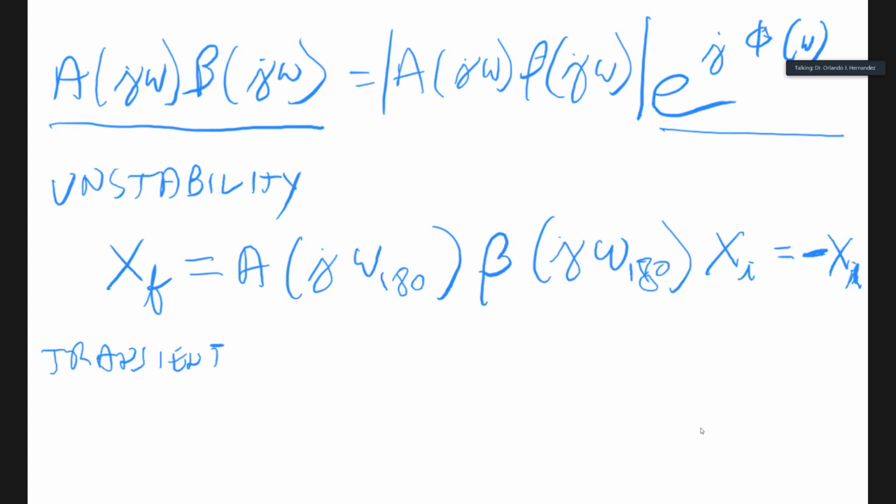Exactly. Those nodes are standardized with those labels. That's just saying that now the error reverses polarity, and now it is feeding with the wrong sign into your basic amplifier, therefore producing a higher and higher output towards saturation or nonlinear behavior. Did that answer the question?